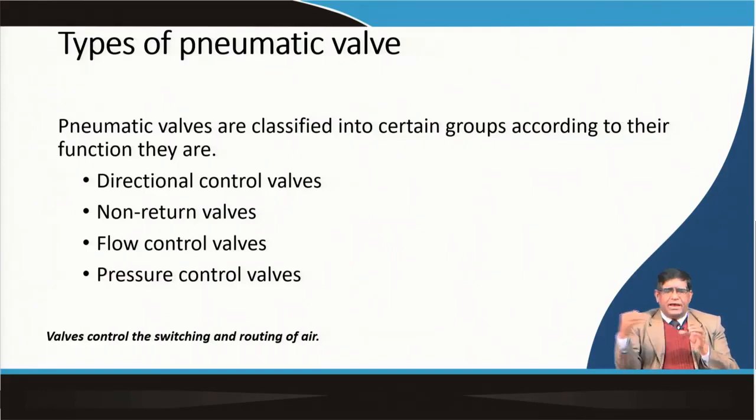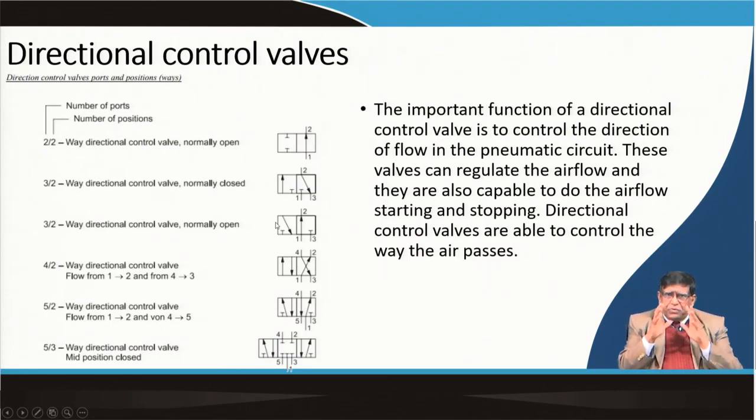So, that means if the air is coming, then whether you are making that same air go to 2 paths and doing 2 operations simultaneously. Say for example, while you are applying a brake to wheels, that means the air will be going and then applying the brake to the 2 wheels simultaneously. Sometimes your air is allowed to go to give your horn, or sometimes you are just applying the parking brake. So, there will be different types of jobs to be done, and these are controlled by these different valves. Now, whenever you see a machine's circuits, what the different types of valves used are is very, very important.